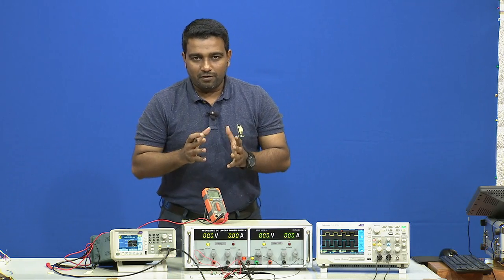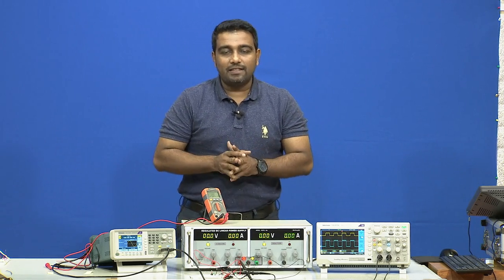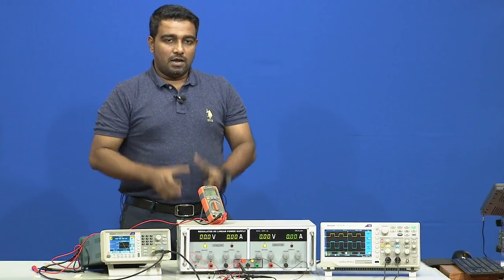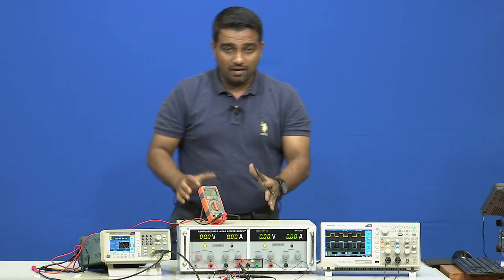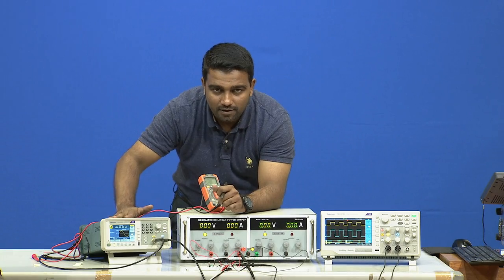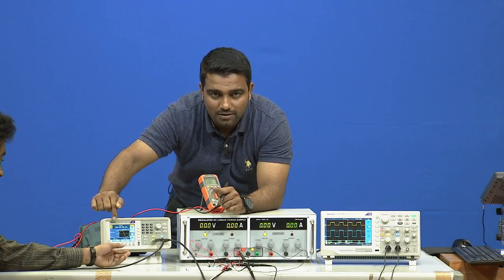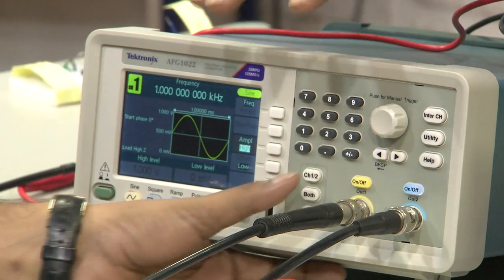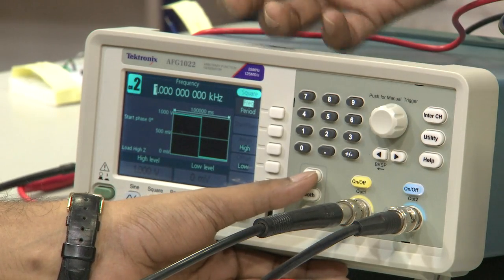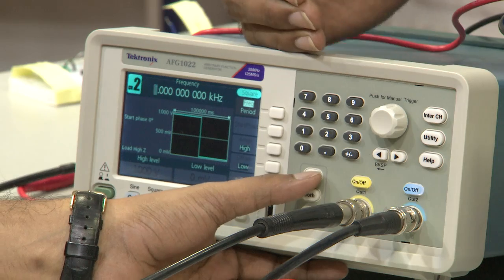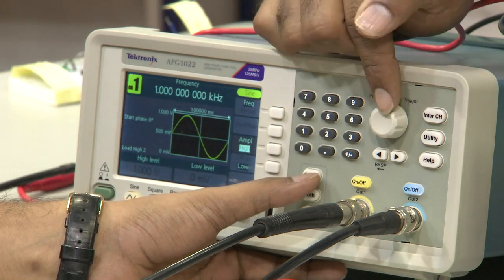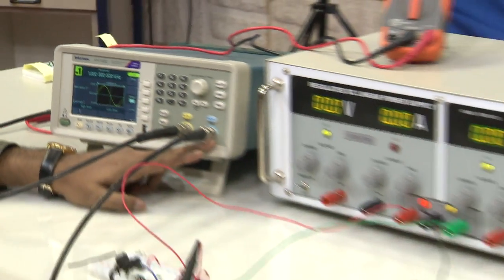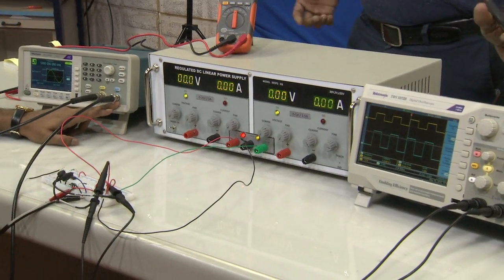So, I told you there was some mistake, and that is perfectly fine. The point is, can we identify what the error in the circuit was. Actually, there was no error in the circuit. What we found is that the display is showing a sine wave, but there are two channels, channel 1 and channel 2. Channel 2 is configured for square wave, and channel 1 is configured for sine wave. Last time we applied a square wave to the circuit. So, when we apply a square wave, we assume we will see a square wave signal at the oscilloscope, and that is absolutely fine.